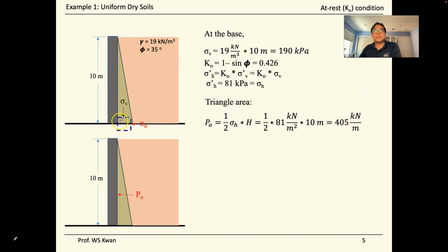So the unit dimension is the direction coming out of and going into the page. So coming out from the screen and going into the screen, that is 1 meter, so per meter, kilonewton per meter. If we know the other axis dimension, we multiply that, then that will be your final resultant force. But now we do everything in 2D.